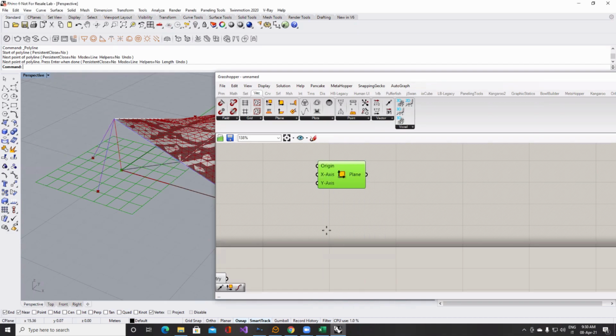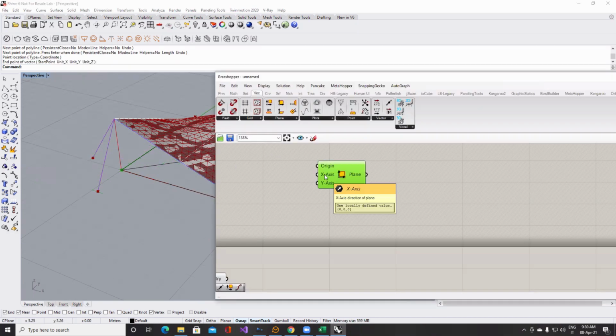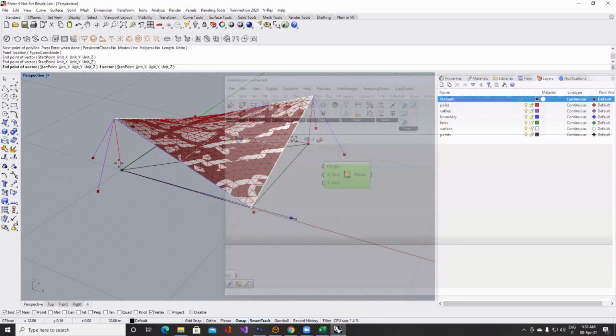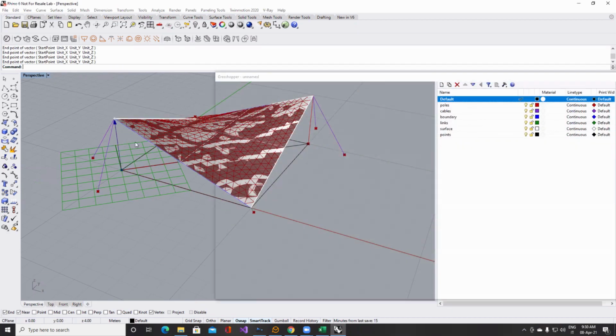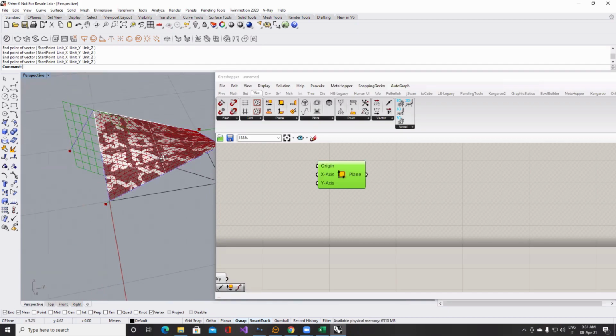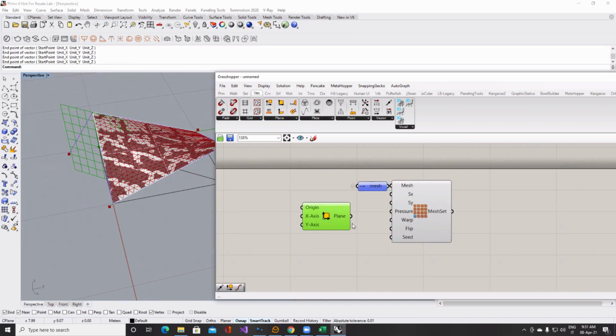The origin is this one here. The x-axis. Clearly, and the y-axis is this one here. Okay, so I have defined the plane that cuts the surface at 45 degrees. And this will be my warp weft plane. Here it is. So with this plane, we define the warp direction.